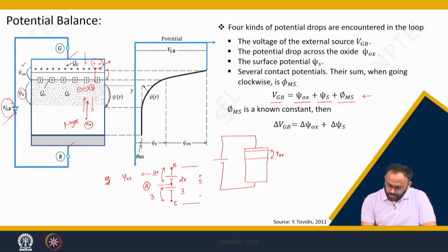Similarly, exactly at this point, from here to there, this voltage is nothing but the surface potential. Now, if node A is positive with respect to C, what amount of charges will come near node A? Because this is positive, the electrons will go there, because we are talking about a metal system. So electrons will only come, but if it is a semiconductor, and that too a p-type semiconductor, what will happen? A negative charge will come up.